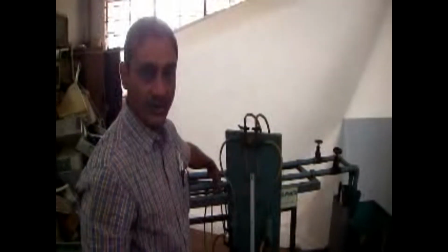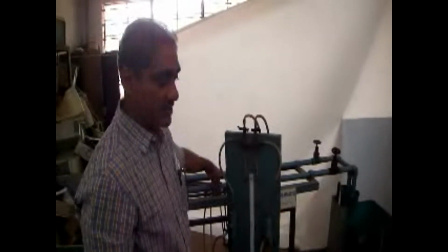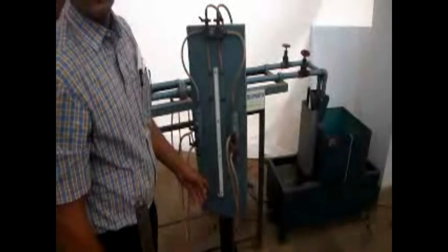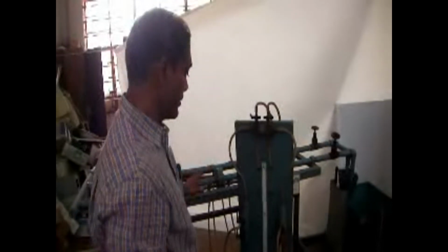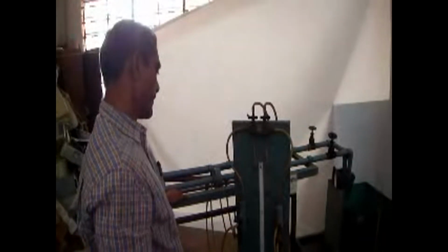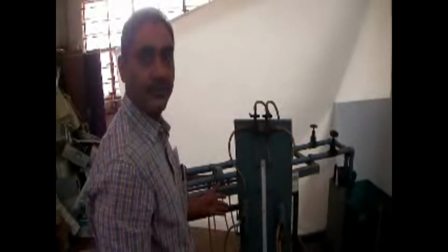Discharge is equal to CD A1 A2 into root 2gH, where H is the head difference, basically between the left and right limb, divided by root of A1 squared minus A2 squared, meaning the size of the pipe versus the size of the opening of the Venturimeter and Orificemeter. Started first through Venturi.